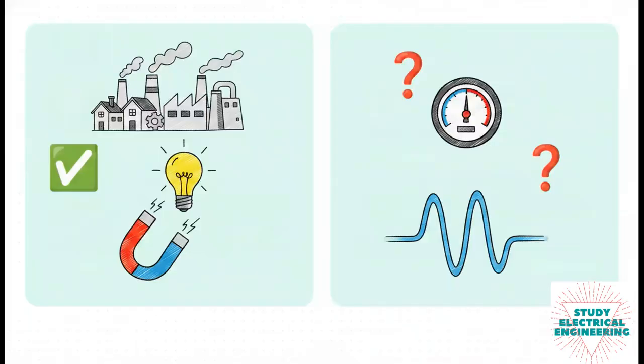At a load bus, a PQ bus, the net flow of real power and reactive power is fully specified and known. Which makes sense, right? We generally know exactly how much juice a city, a neighborhood, or a big industrial plant is pulling. So that leaves our unknowns. The variables we actually have to crunch the numbers for here are voltage magnitude and phase angle.